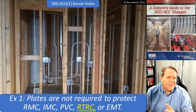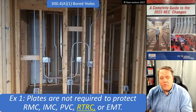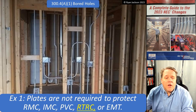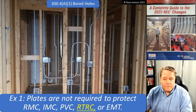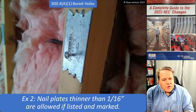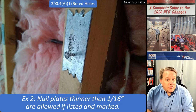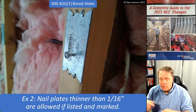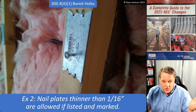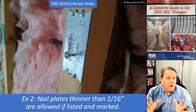So we just cleaned up this section to use the terms that we've been using for the last 10 or 12 years in the code. So again, nail plates are not required to protect rigid, or IMC, or PVC, or reinforced thermosetting resin conduit, or EMT. We still have the same exception that says nail plates thinner than 1/16 of an inch are also allowed if they're listed and marked. Nail plates do not have to be listed. That's not a requirement. You can use any piece of metal that's 1/16 of an inch thick. I should say any piece of steel that's at least 1/16 of an inch thick.